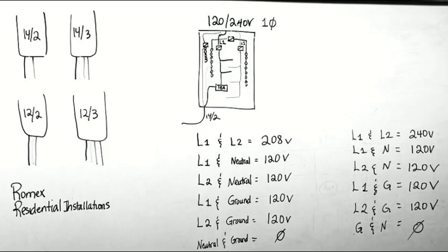Because my circuit has the capacity of 15 amps and I'm barely using about. Oh, okay, yeah. So this is how we calculate what size of wire we're gonna use in a home, right? What is our load and how many loads are we going to have on that circuit? We do that a lot for lighting. Then for other loads, like for example, receptacles, we can't really do that. The code just gives us a maximum amount of receptacles that we can put on a 15-amp circuit and on a 20-amp circuit, because we don't know what's gonna be connected to.